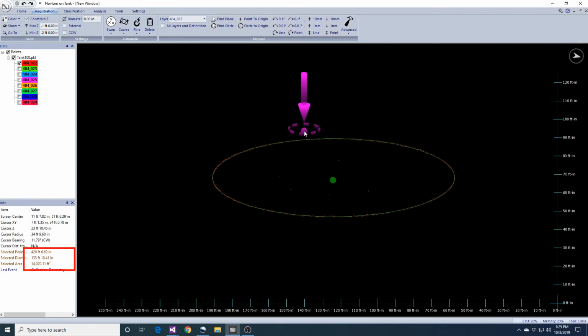You can use the Circle Find tool to not only estimate shell diameters, but also column diameters and areas. Using the layer control here, you can also select whether you use data from all layers or just a single layer. All these controls within this area apply only to the layer that is selected. Since our data is not yet registered, we only want to use the layer that we used to trace our circle.